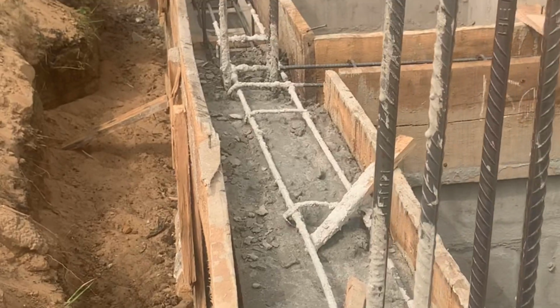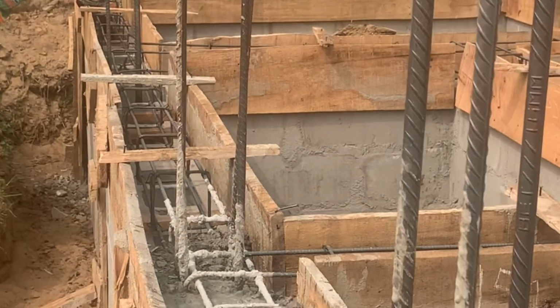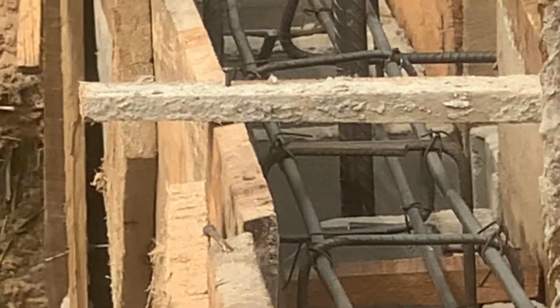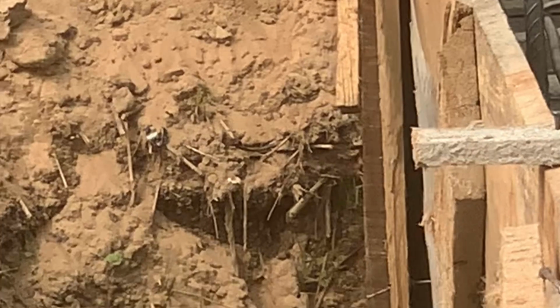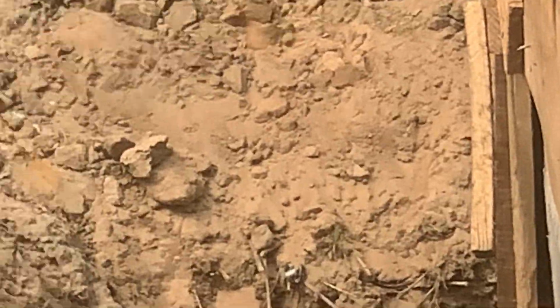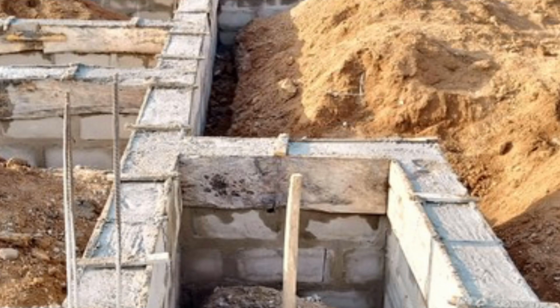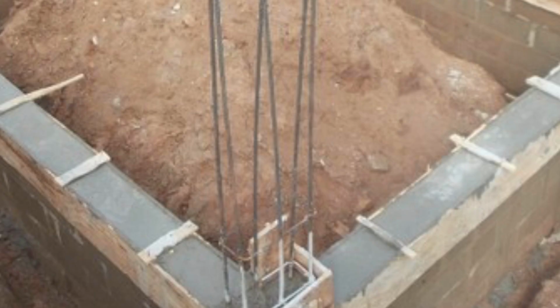The concrete should be mixed very well with good quality water that is free from every form of impurities before casting. The pouring of concrete should be done gently and well vibrated in order to avoid honeycombs at different areas of the column, as you can see. It is advisable to allow the concrete to cure very well before removing the boards. Okay, and most times within 24 hours to be removed.